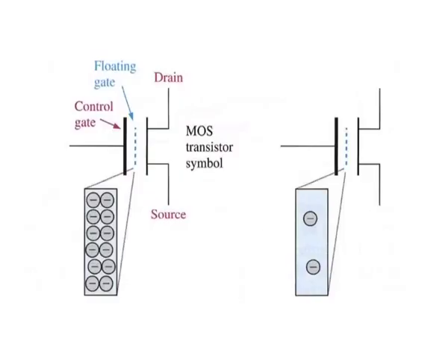Flash memory cells. A single transistor cell in a flash memory is represented in figure. The stacked gate MOS transistor consists of a control gate and a floating gate in addition to the drain and source. The floating gate stores electrons as a result of a sufficient voltage applied to the control gate.